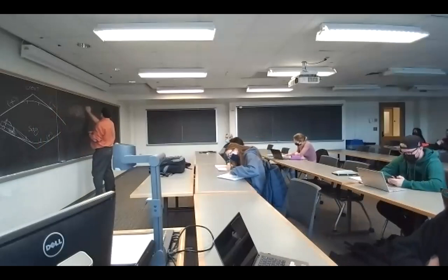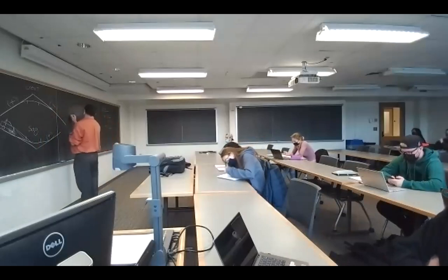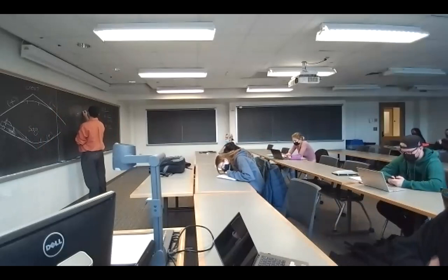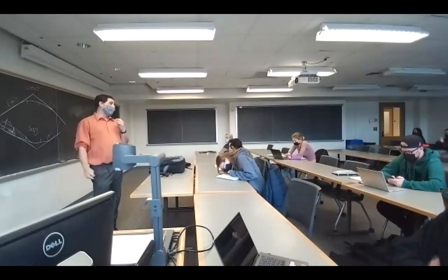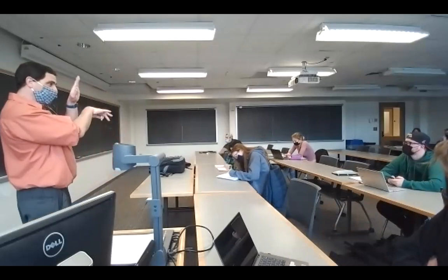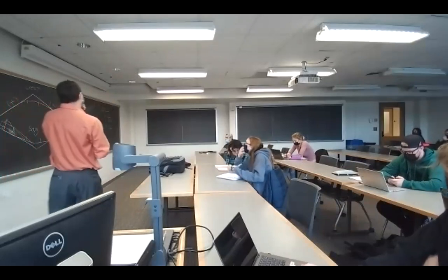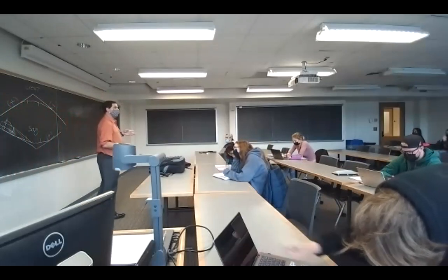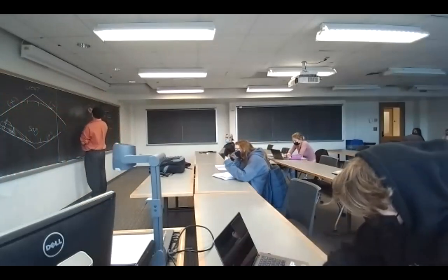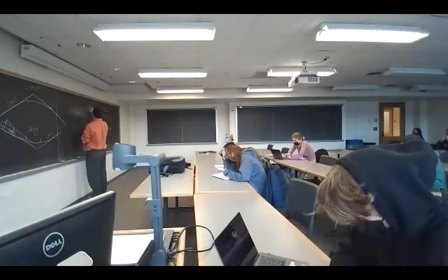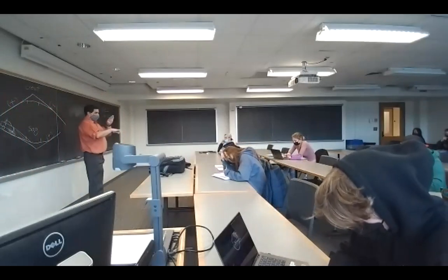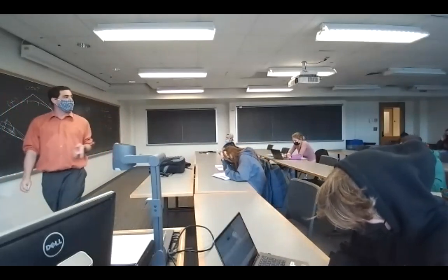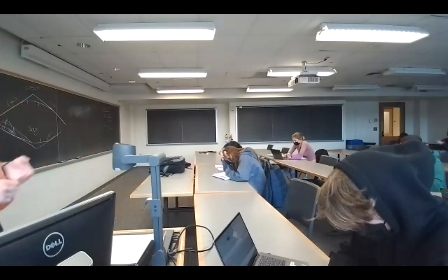What about in my subdivision if I only have a slight change? Like if I just have a little kink, if it's less than 1%, the township isn't going to make you a vertical curve. So long as that difference in grade isn't greater than 1%, you can get away without one. Okay.